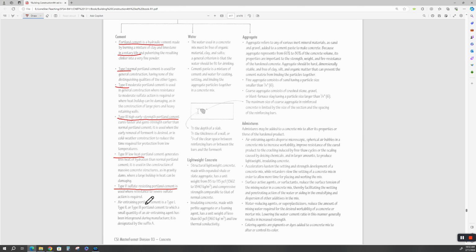All right. Now, remember me telling you about the reinforced concrete sewer pipes and how the sewer gas, which is hydrogen sulfide, would rise up to the top of the pipe and mix with the condensed water and turn into sulfuric acid and eat away at the cement, the calcium carbonate, and destroy it. And then the aggregate was exposed, and then the rebar gets rusted, and the top of the pipe falls in, and bad things happen. People's backyards sink.